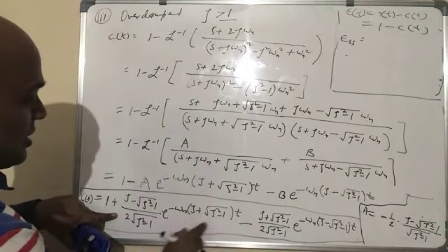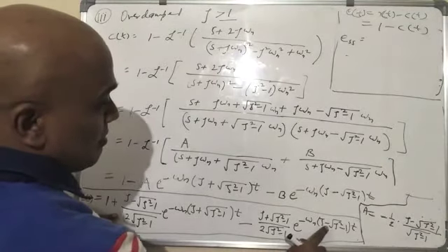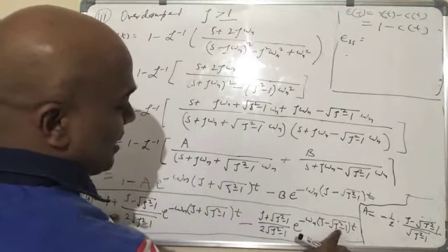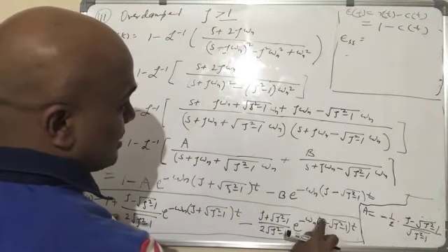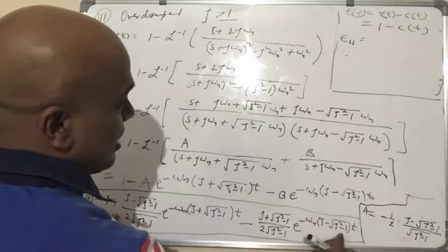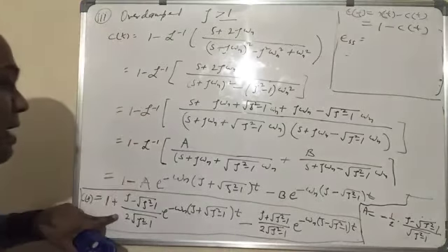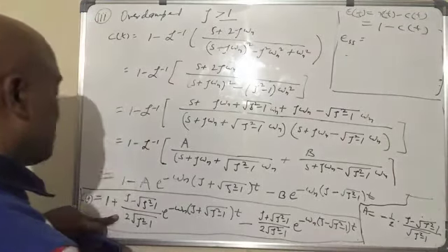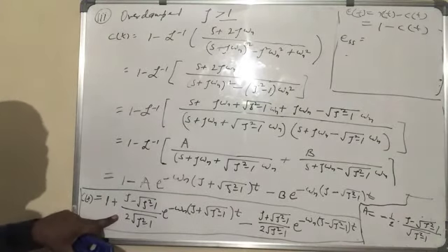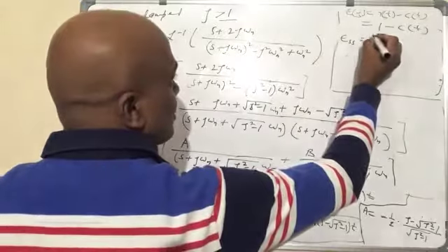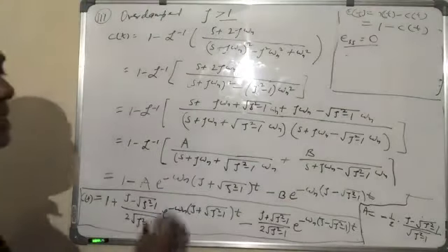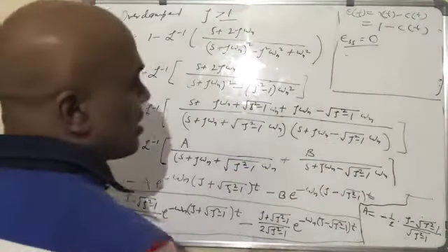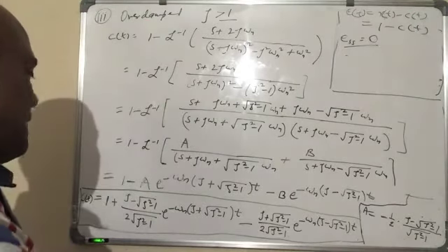So at t tends to infinity, this becomes 0. Here zeta minus root zeta square minus 1, so zeta square minus 1 is less than zeta square, hence zeta minus root zeta square minus 1 is a positive number. So this also is positive number, and from here to here, so total thing is a negative number, and hence with t infinity this will also be 0. So what you get in that case is it tends to 0. Yeah. So in this case also what we see is the steady state error will be 0, but it may take longer time to achieve rt.